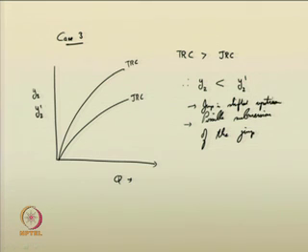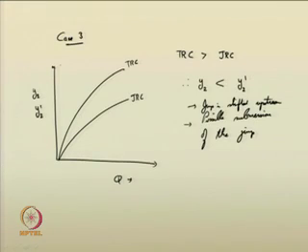So, possible submersion of a jump can also be encountered in such situations. By providing proper sloping aprons, you can have effective jumps in this situation. We have seen that such jumps are not efficient; they cannot dissipate energy. If you want to design stilling basins for energy dissipation, such jumps cannot dissipate that much energy, but by providing proper aprons and sloping aprons in the upstream location, you can have a better jump.